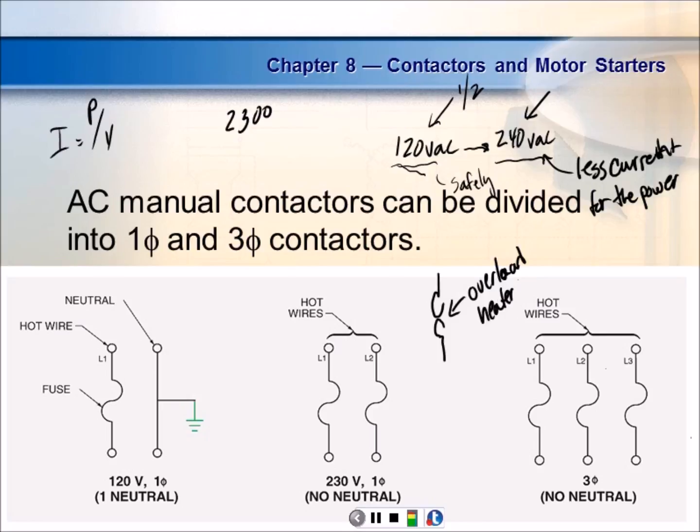So normally on single phase systems, low voltage single phase, we only fuse one side, because this side right here is referenced to ground anyway, right? Don't understand what I'm saying? In your panel box, it carries current, but there's no potential. If you got between ground and the neutral in your power system on your low voltage side, you wouldn't get hurt at all, if your ground was correct. If your ground was screwed up, you could.